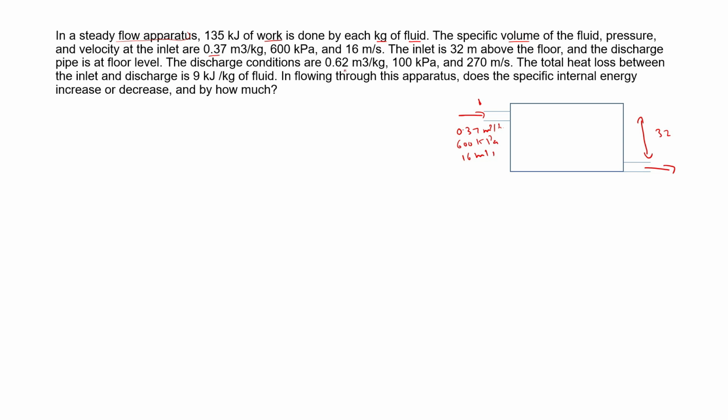Discharge conditions are 0.62 meter cube per kilogram, 100 kilopascal and 270 meter per second. The total heat loss between the inlet and discharge is 9 kilojoule per kilogram of fluid. The question they have asked: in flowing through this apparatus, does the specific internal energy increase or decrease, and by how much?